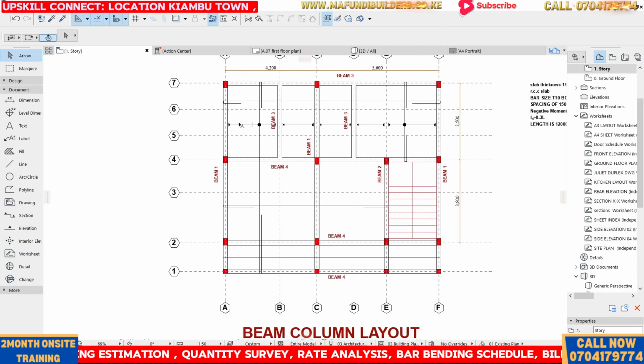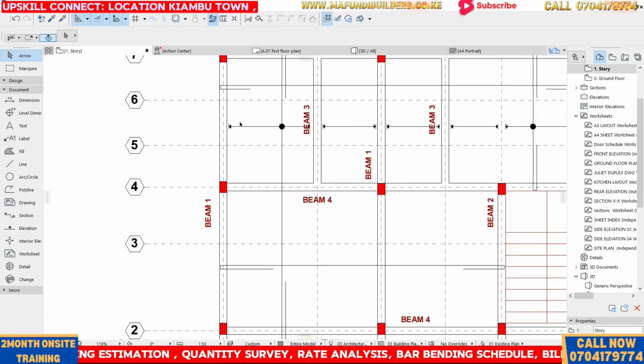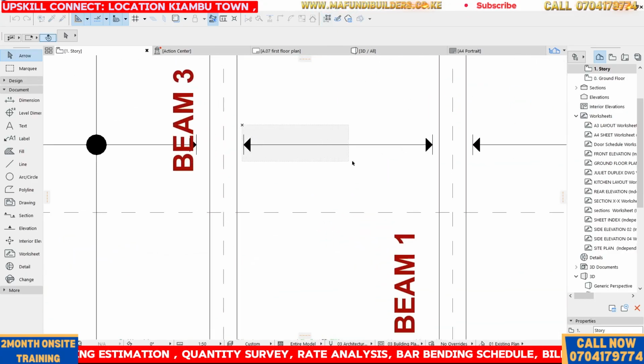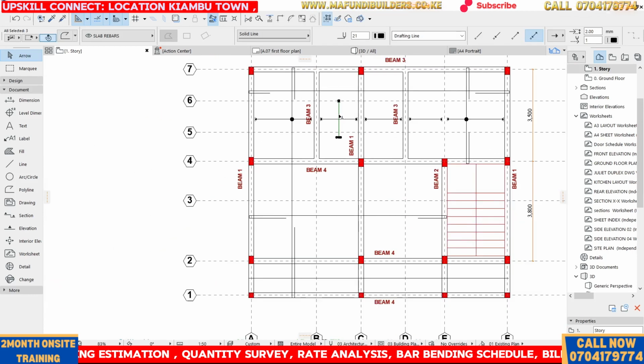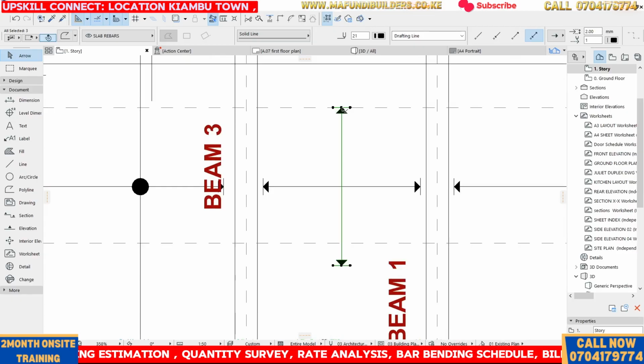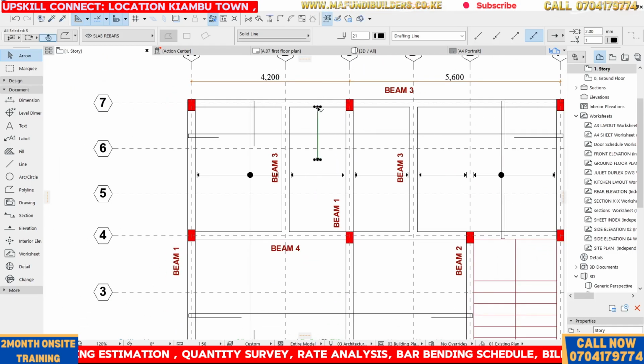Now, let's continue by showing the distribution for these two, this one and this one. Because of time, I don't want the video to be so long. So I'm going to pick these two, and I'm going to rotate a copy by Control Shift E. Yeah, so that's how you're going to rotate. So now this one is good. What I'm going to do, I'm going to drag this first of all. So drag it all the way here and then move it away by 50, as we said.